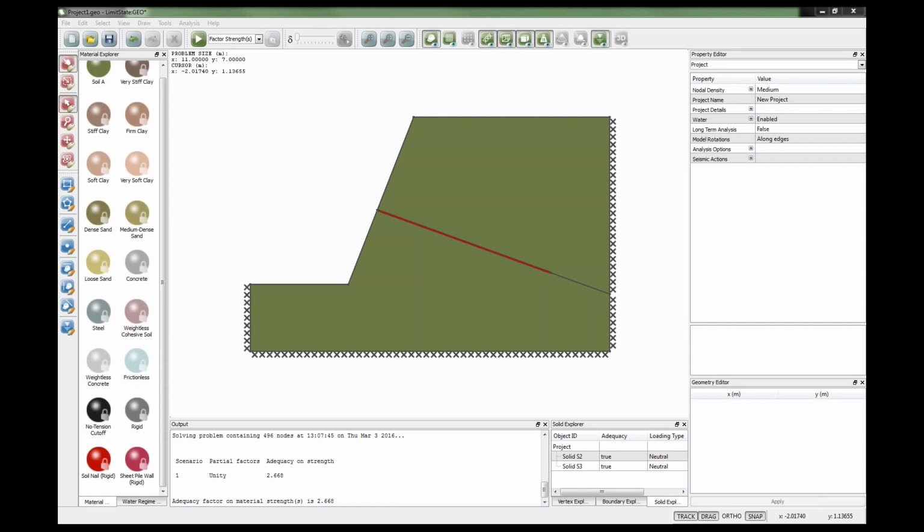If you're looking at ground improvement, you can model the effect of ground improvement, whether that's just generally increasing the strength of the material, or putting inclusions in that increase the strength locally, so you can easily model, for example, stone columns or suchlike. But again, you'll just be assessing on strength in this case rather than on settlement.